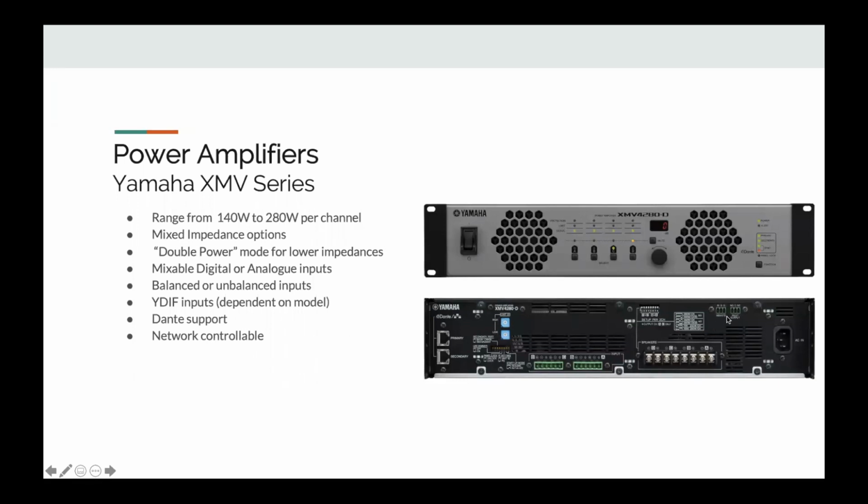And in the right-hand side of this picture at the bottom, you can see that I've got a remote connection, an MSG. The M represents mute, the S represents standby, and G represents ground. Should you connect S to G, the amplifier will immediately switch off. And should you connect M to G, the amplifier will automatically mute. That gives you the advantage in commercial environments when you're having to interface, because of law, with things like fire safety systems. You can very easily connect the two together without any level of programming to make sure that when a fire alarm goes off, the music stops.